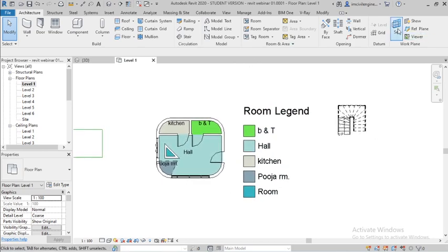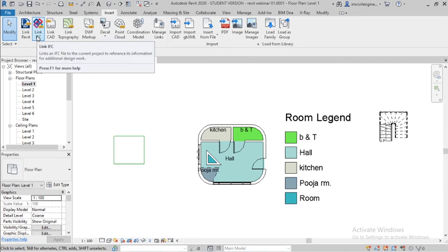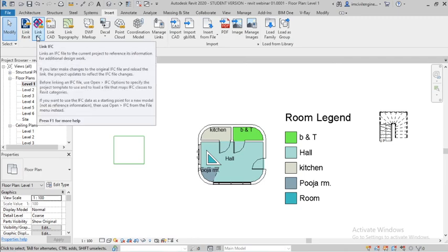So that's a reference I have also explained, and next comes Insert. You can insert files, insert from file, PDF, manager, anything you have to insert, Revit files, IFC. IFC will be easy if you are using Tekla Structures. You have to save the file as an IFC link. If you are opening it in Revit Structure, it will come with IFC links. And if you change anything in that file, it will change automatically in Tekla Structures also.